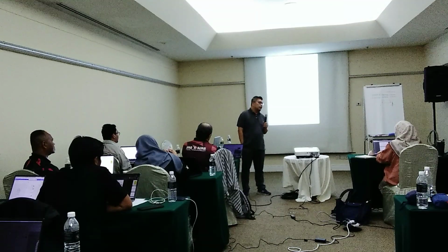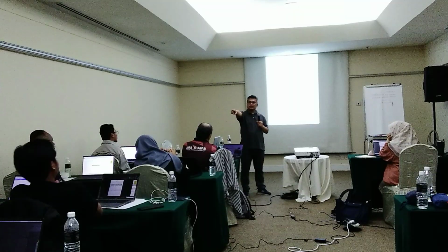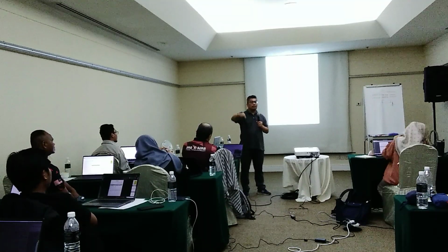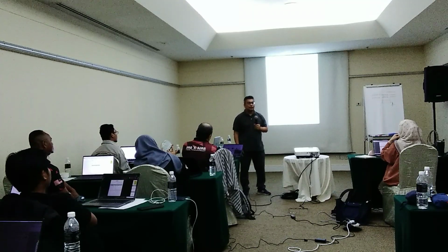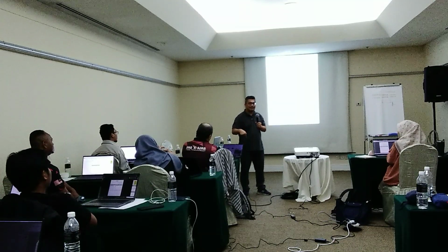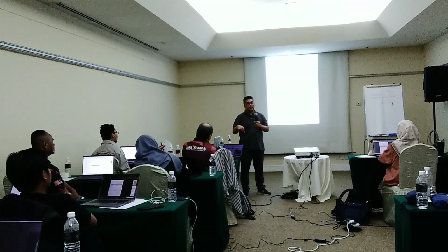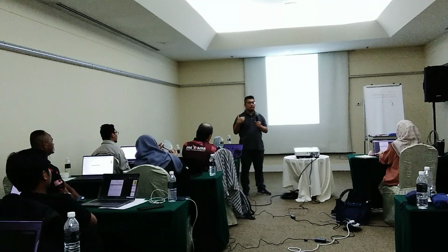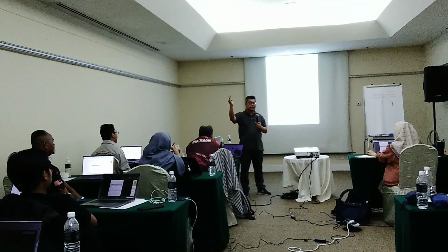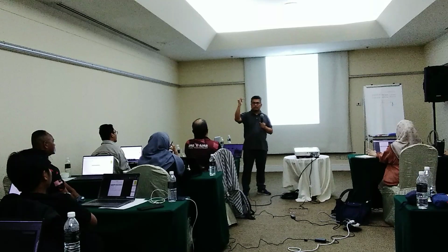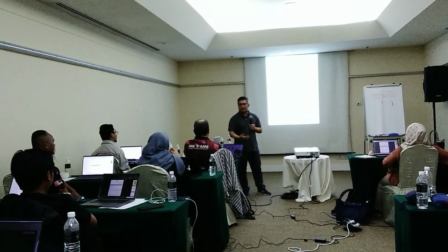Say your severity is 9, like just now, right? Just now the severity was 10, but the RPN was only 40. So you need to immediately reduce the 10. You need to take actions to reduce the risk, whether it is severity, frequency, or detection. Okay? You need to continue until